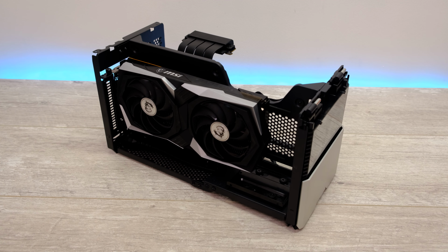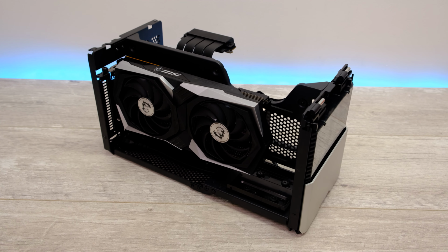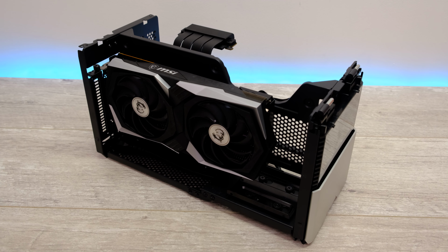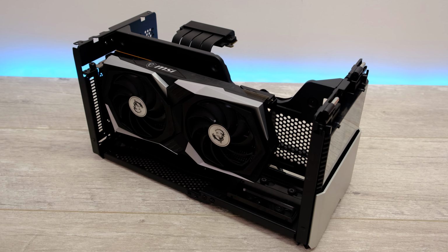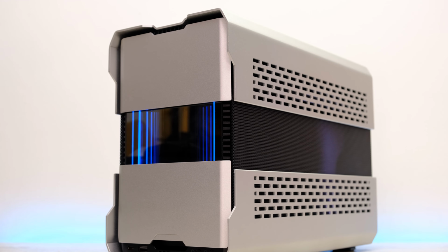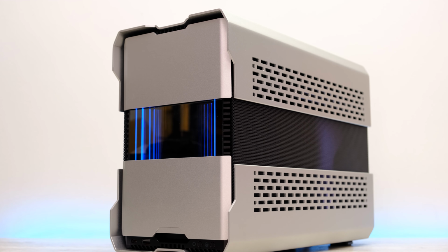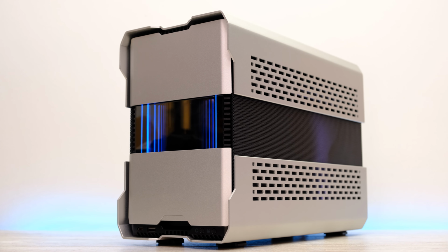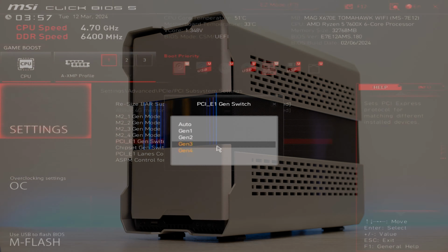However, there was a Gen 3 riser cable stuck between them, and when you mix those three components in that combination, your system goes haywire. I was wondering what the heck was going on. There were thousands of comments on Reddit about the same thing. Turns out it was the fact that you're trying to run a Gen 3 riser at Gen 4 speeds.